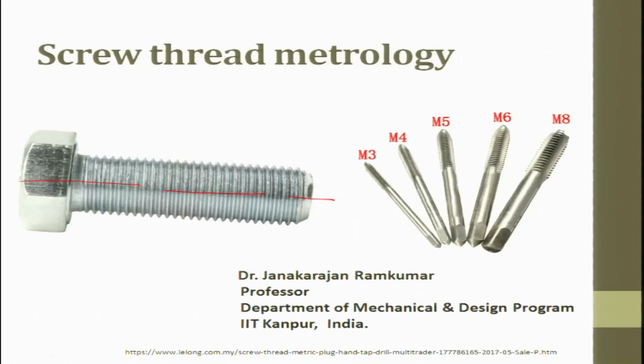And if you look at it, you should understand that a screw thread is not like a standard flat shaft. For a standard flat shaft, it is easy to measure the diameter. Here it is a thread which runs, so you have a peak, you have a valley. Now when you try to measure the distance from here to the next pitch, maybe there will be a variation. Or if I try to put a flat plate on a line, there might not be perfect flatness in contact. So, the standard measuring devices cannot be used.